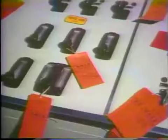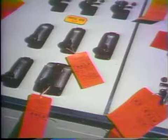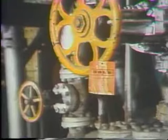The way this is usually done is called tagging or tagging out. Every plant has specific tagging procedures that must be followed to ensure the safety of maintenance crews. Basically, when a system is tagged out, the operator places a color-coded tag on the components that isolate the equipment which is to be worked on. That is, tags are put on all components that could create a hazard if they were operated while the maintenance crew is at work. A piece of equipment that is tagged for personal protection should never be operated until the tag has been removed according to plant procedures.